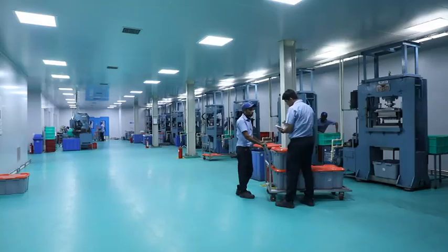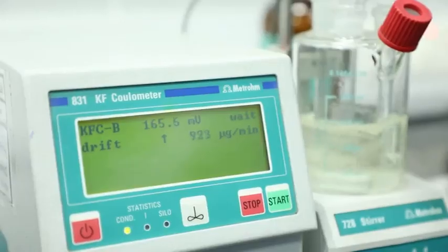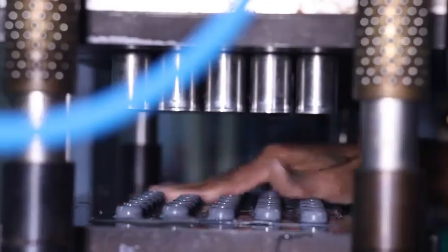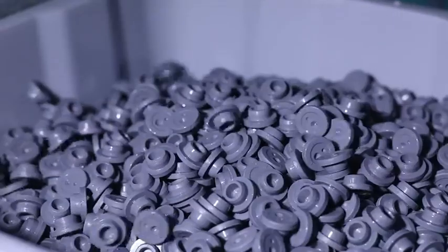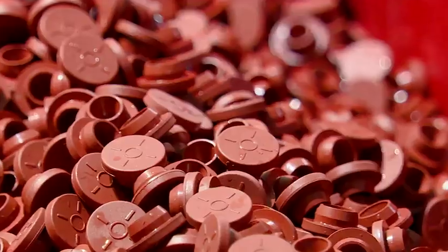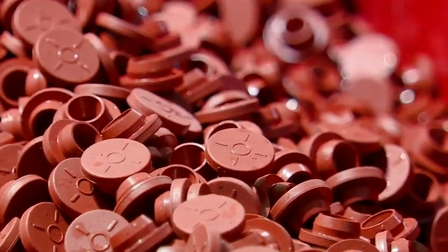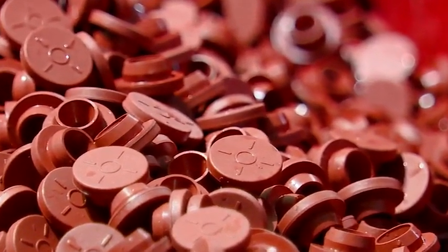In-process quality checks are conducted at this stage also. If a large number of the trimmed produce appear to be defective, necessary corrective actions are taken. For example, sharpening the die or grinding, which eventually corrects the defects.